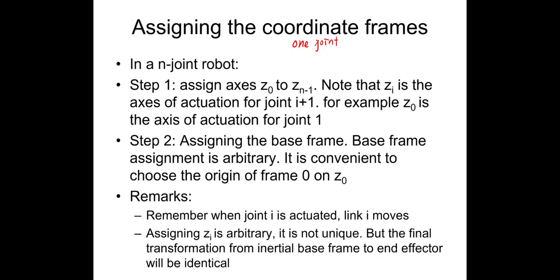But anyway, each joint can be controlled by a motor, and this motor can be controlled by something. If we talk about the overall robotic arm analysis, first of all, we have to define the coordinate frames by ourselves. For example, I directly give you a robotic arm, you look at the geometry and the real arm, and we want to do the analysis. First, we need to define the coordinate frames, one for each joint, so that we can start. To assign them, we have 4 steps.